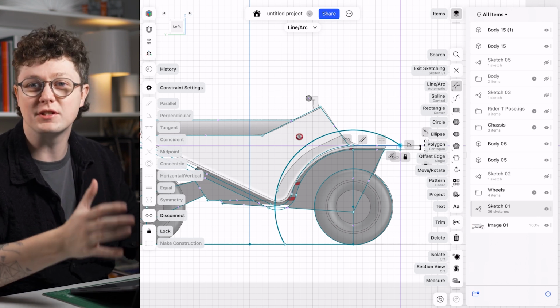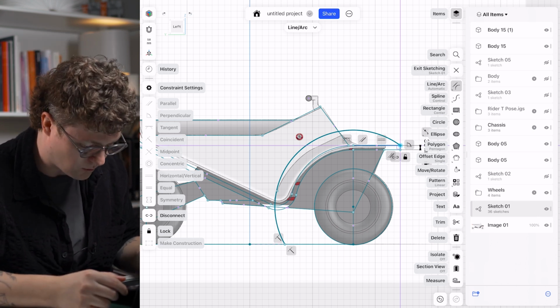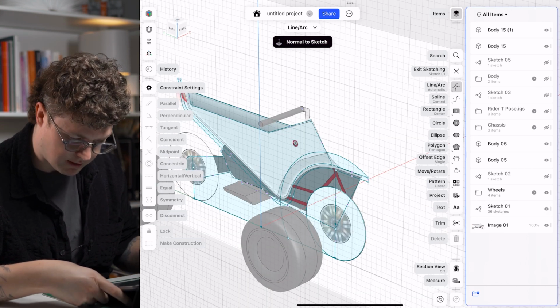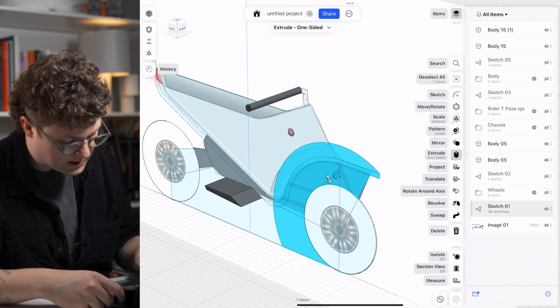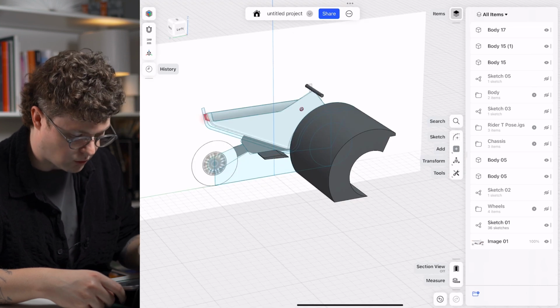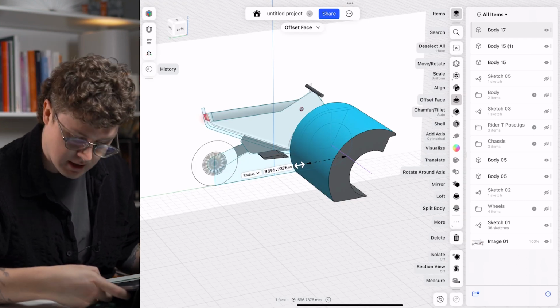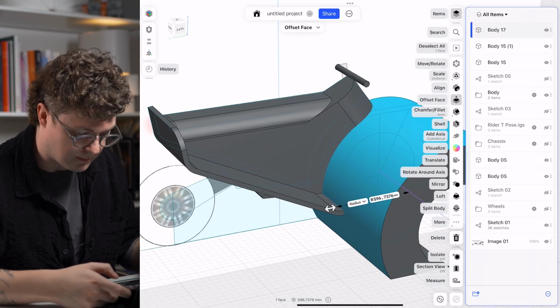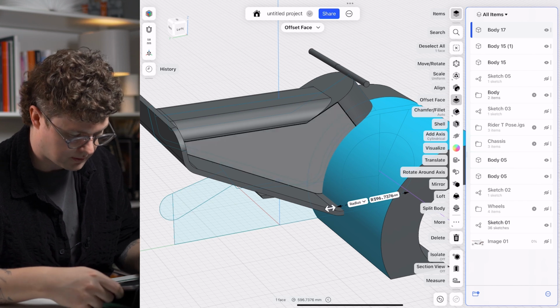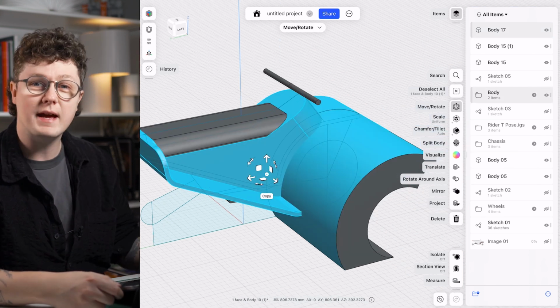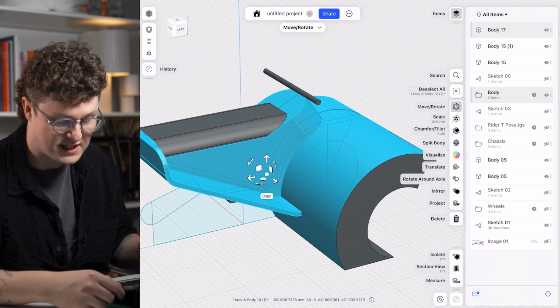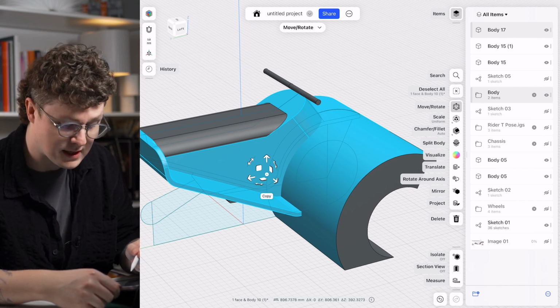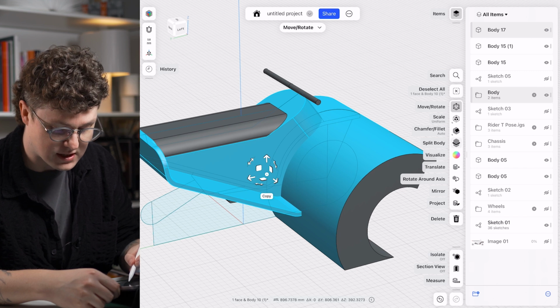We're using this to start cutting up the object in more ways. It can hide everything that we don't need, pull out this, and we'll use this as a throwaway body for this particular surface. So what we'll do, we'll show our main body, double click it. So we have the main body that we want to split fully selected, and we have the splitting profile selected in that face. And you'll notice that it now says split body.